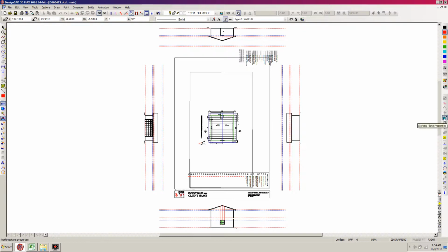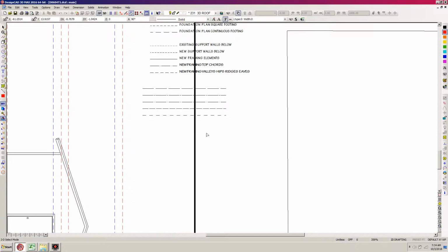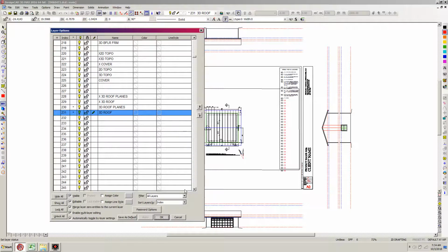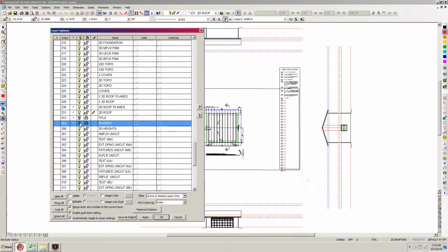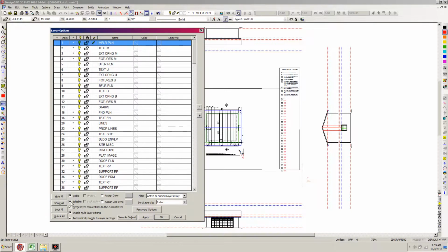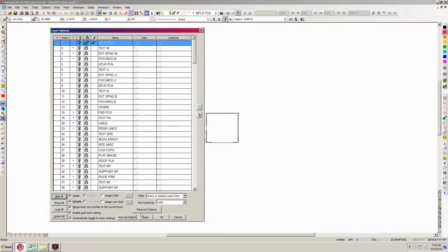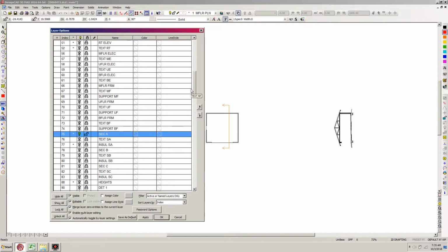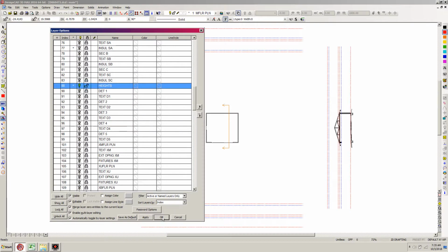And I'm going to turn this guy around, just reset working plane, Control W, go to layers, hit L for layers, and I'm going to have just active or named layers only, and I'm going to scroll on down. I don't need to have the title and border up right now, so I'm going to close some of that stuff down. Actually, all I really want at this point is the floor plan, which is in layer 1, and I also am going to be moving those in layer 1 into 101, layer 2 into 102, and so on and so forth for these existing main floor layers, because I'm going to be drawing in layer 1 in a short time up above here. Actually, it'll be layer 5 because it'll be upper floor. So what I want to do is I also want to call up the section drawing, and also the elevation lines, because I want to get kind of an idea of heights involved here.